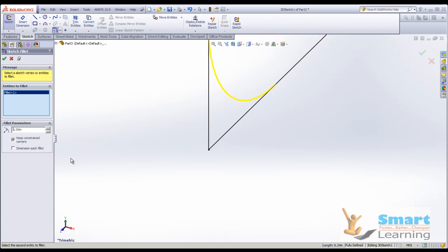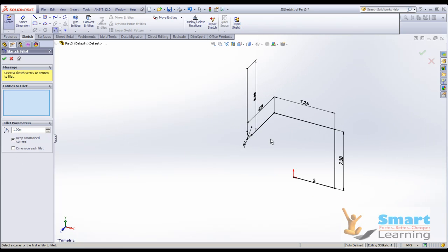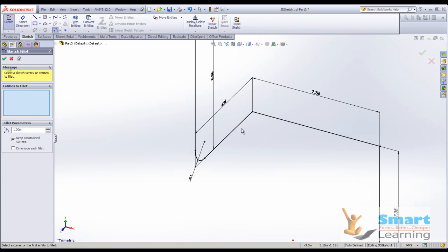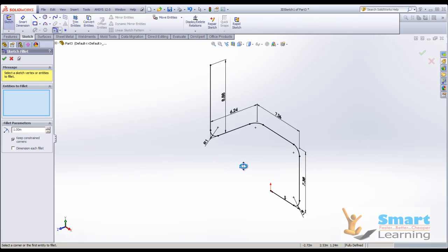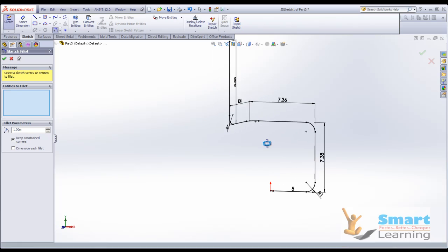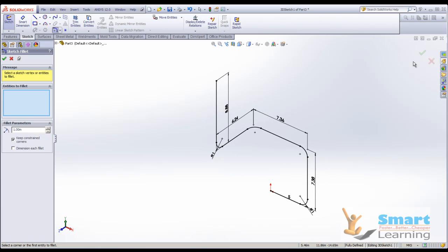You can create this over your profile. Maybe this control you can do, where you can create your 3D profile. Just use your tab key to switch the direction, then you can create your profile and just sweep it.